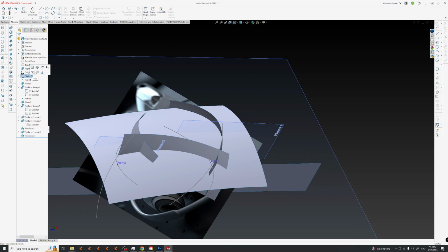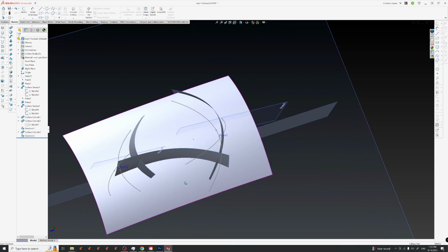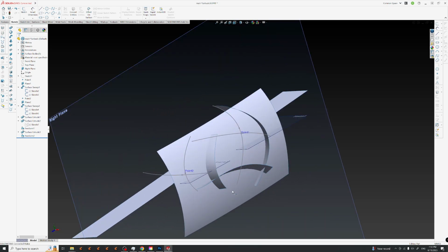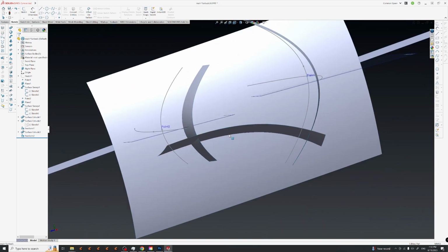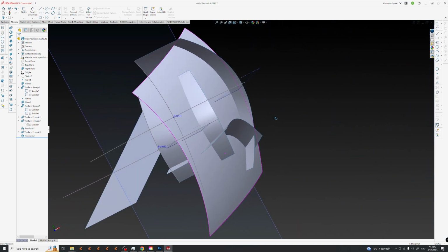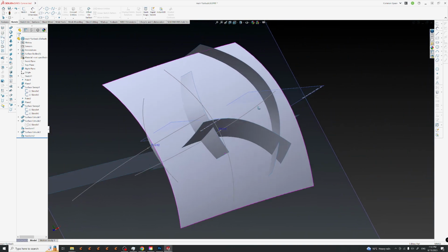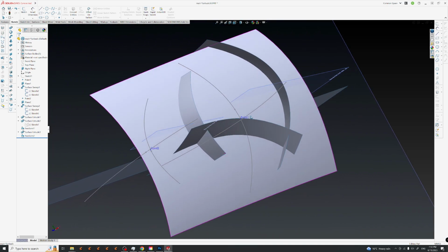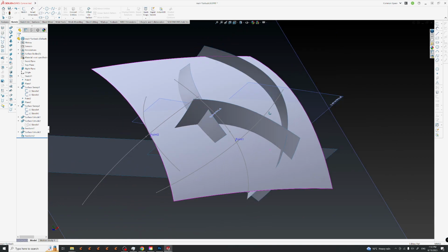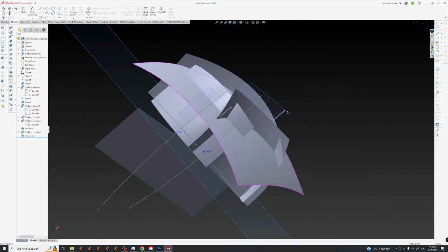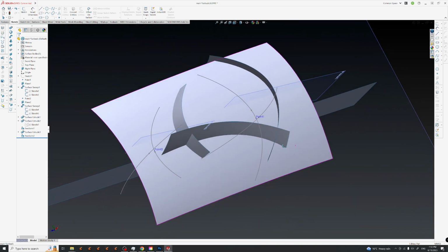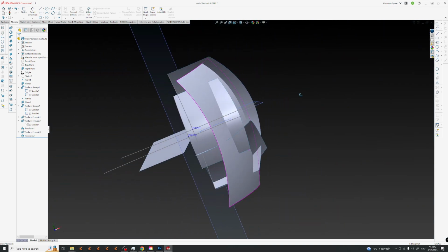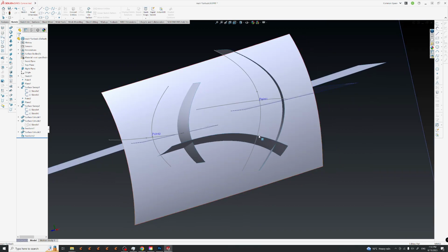Let's hide this picture in here and let's blend them in. Now, from what I saw in Solidworks, it's not so stable when you use fillets straight from the surfaces. Now, in Catia it is very stable, but Solidworks, yeah, not so stable.